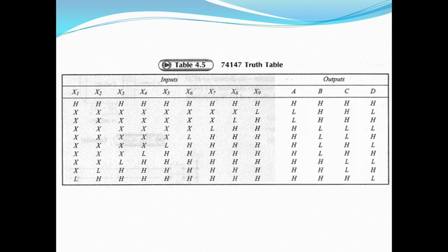Here, when none of the switches is closed, what happens? All inputs are going to be high, so none of the inputs is activated. That means all the BCD outputs A, B, C, D are going to be in the high state.